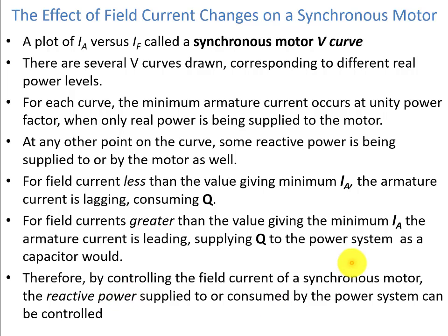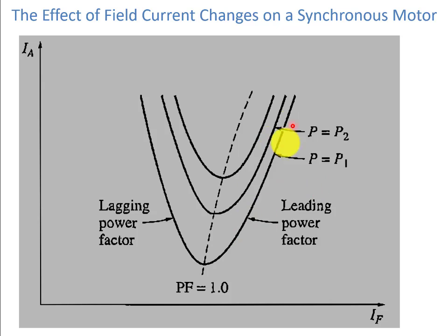Therefore, by controlling the field current of a synchronous motor, the reactive power supplied to or consumed by the power system can be controlled. Here you can see this in this graph.